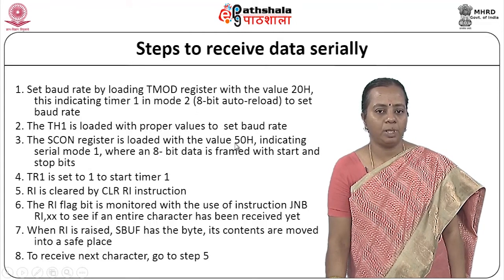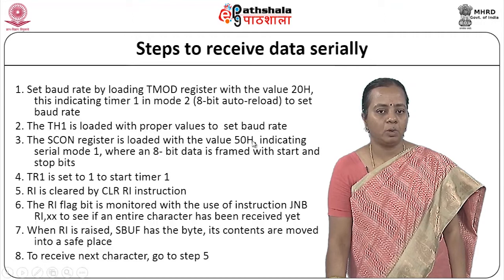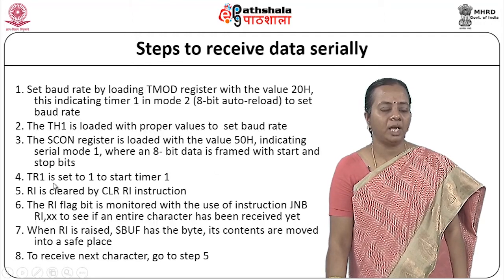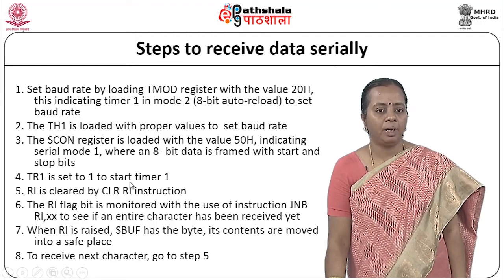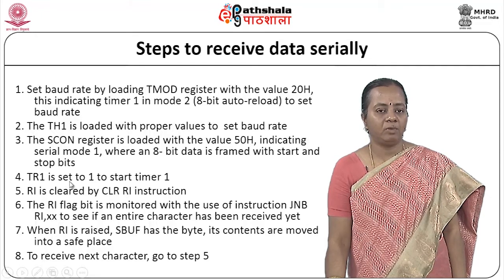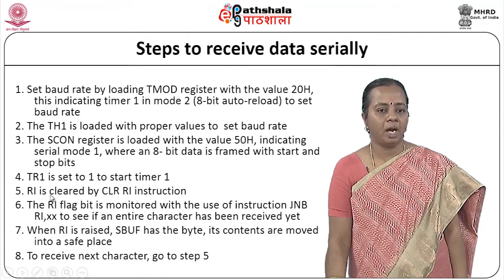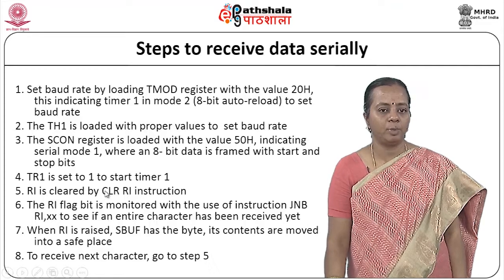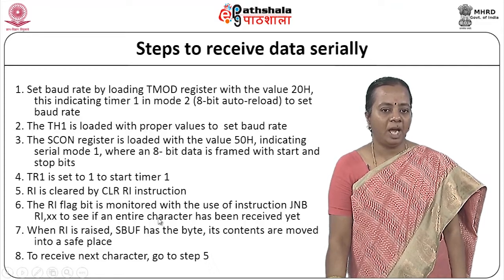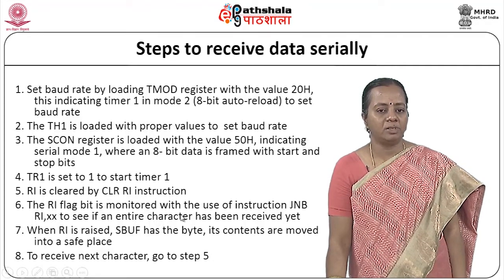For that we use 50, and TR1 is set to 1 to start the timer. The RI flag is cleared, because before starting the communication we clear the RI flag. After that, RI is continuously monitored.